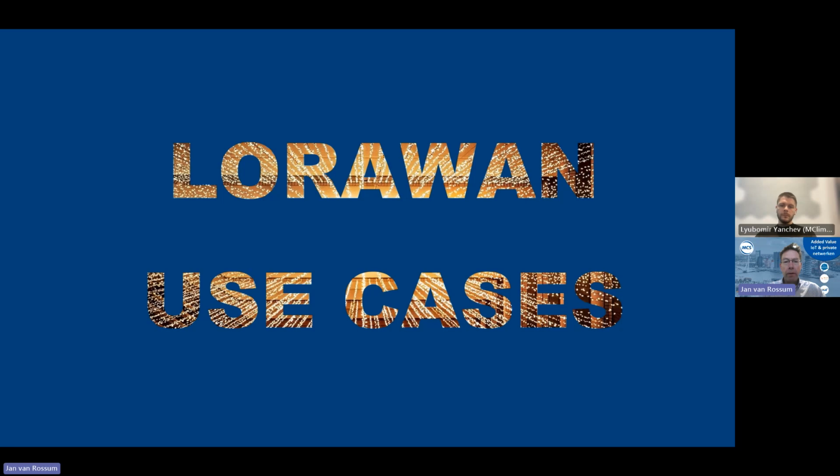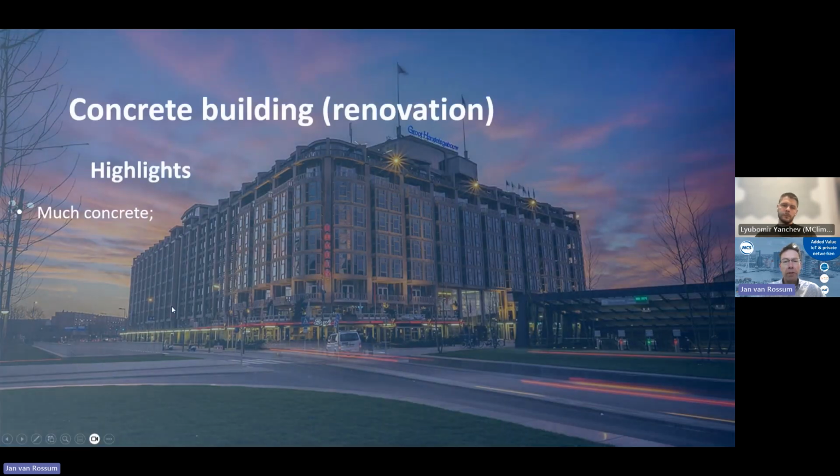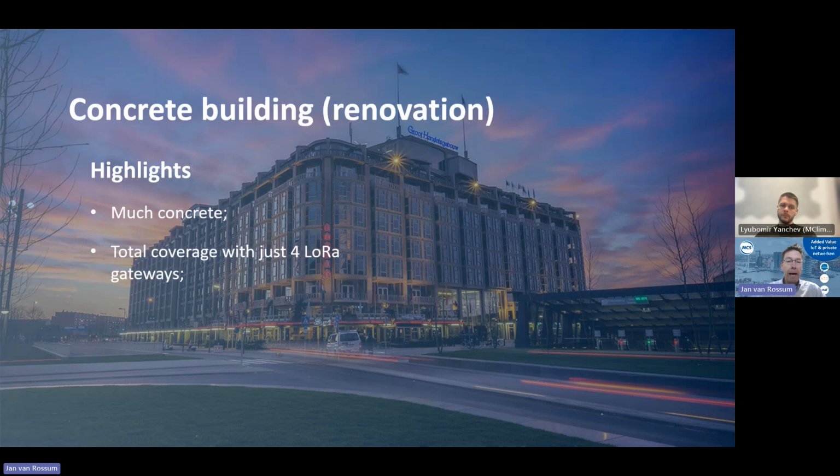So, okay, if you talk about a use case, for example, we have here a very large building. It's in Rotterdam. It's a very old building. And as you can see, it's a very dense building. It has a lot of concrete. So that's actually pretty much of a challenge to get it covered, we thought. However, we did measurements for LoRa. And there you see that with only 4 gateways, if you place them in a good situation, you get the whole building covered. That's actually pretty incredible with such a large amount of concrete.